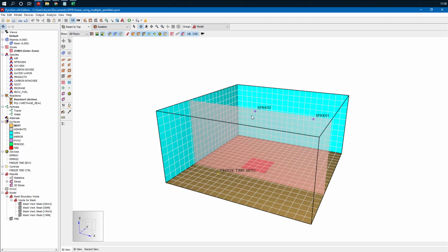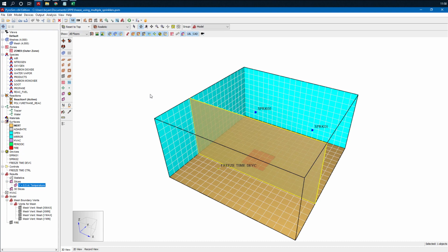I don't necessarily want to use the extinguishing coefficient to determine how many kilograms of water mass accumulate per square meter over time on the burner surface. I just want to say, I'm going to make the assumption that if any sprinklers activate, then wherever the heat release rate is at that point, we're just going to hold it. We're not going to diminish it. It won't continue to grow. We're just going to assume that the sprinklers can suppress and maintain that same heat release rate. So that's a more common use case for this feature.